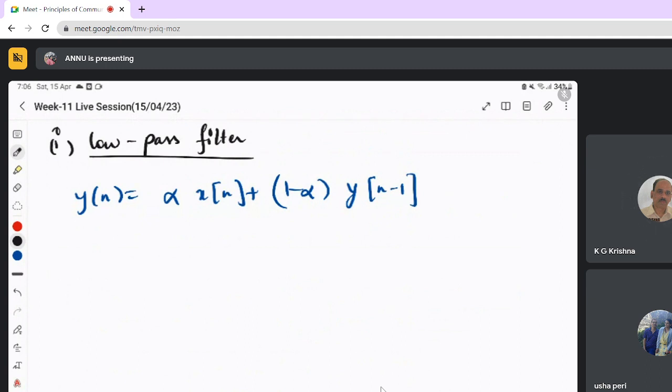But for some examples, I have taken some examples of how we will say this is a low pass filter and high pass filter. This is an example of an LTI low pass filter. Yes, every filter can be considered LTI because it has those properties. My next clarity is modulator. A modulator is nothing but multiplication of signals in the time domain, right? That multiplication process is simply a multiplication.